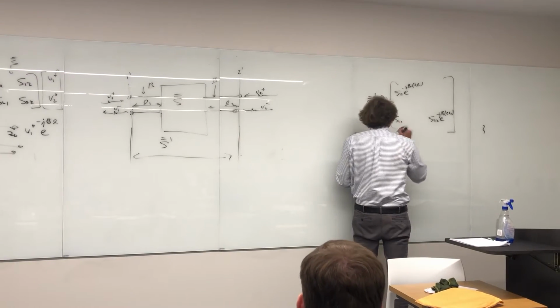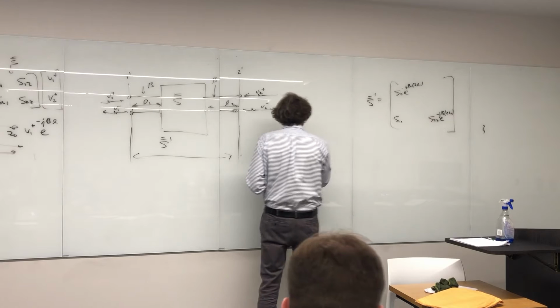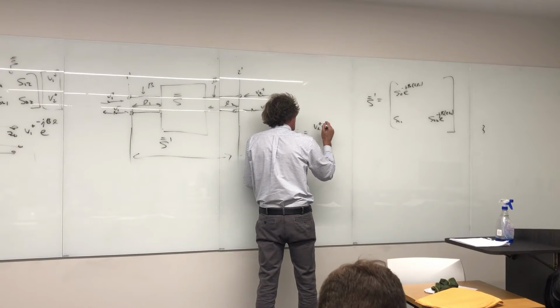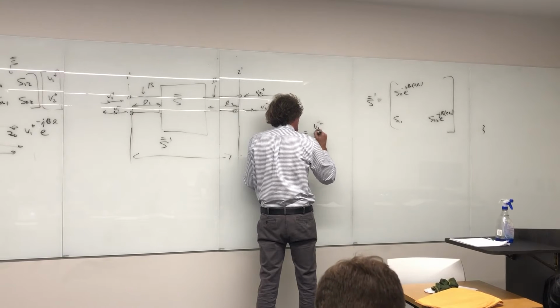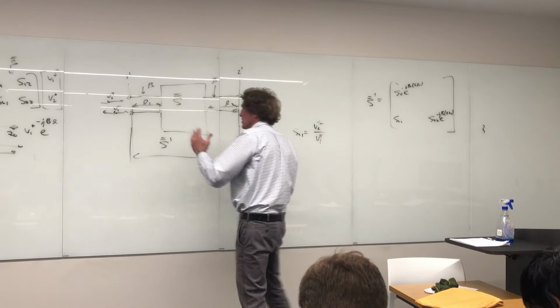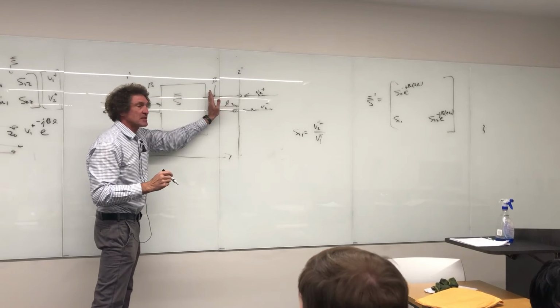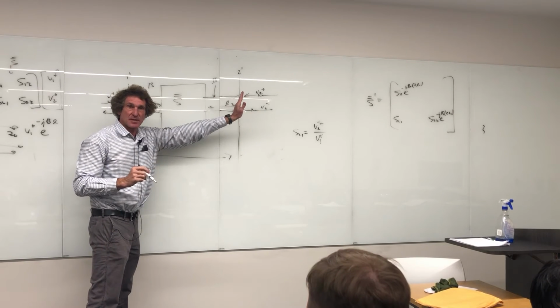Now, what about S21? Well, S21, in case you don't know it, that's what? V2 minus, pardon me, over V1 plus. So it's really what? If I put V1 plus here, it's how much of that signal comes out here as V2 minus. Correct, class?